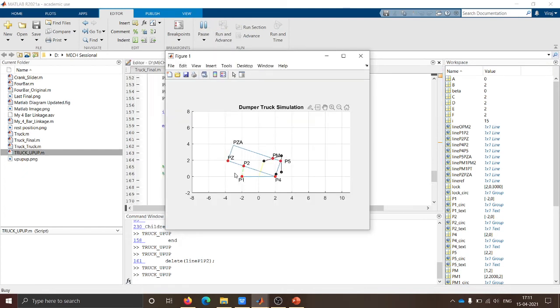As the length of the actuator increases, the angle beta also increases, and as beta increases, the point PM will have a tendency to move in the X direction, but as it is attached to a link, this black point here will also move in the X direction. The black point is attached with an inextensible string to the base of the body, so it follows a downward facing path, which in turn causes this black point here to go upwards, and ultimately leading the gate to open.